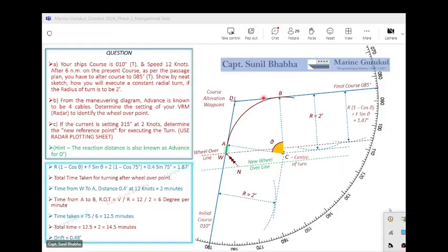You will be reaching somewhere onto the west of point Bravo here, but certainly with zero cross-track error. If you had started at November, you will be exactly reaching at point Bravo. Now, since we have started a little west of November, whatever is the distance here, the same will be the distance between the point Bravo and the point where you hit your final course.